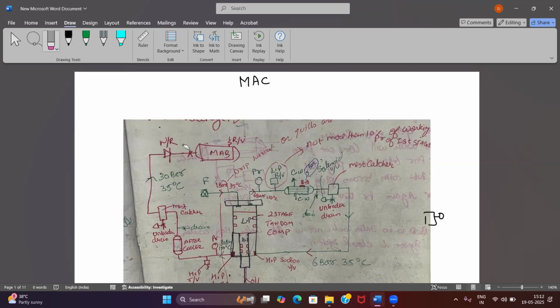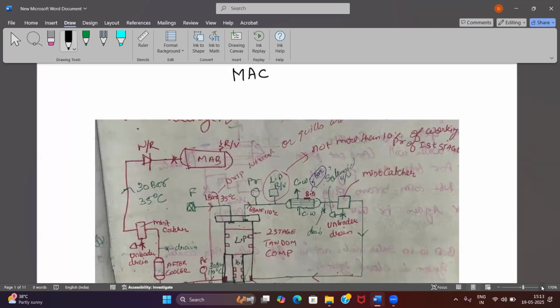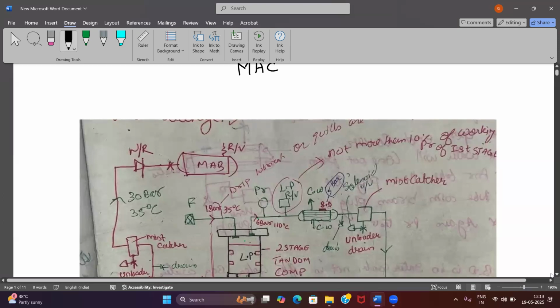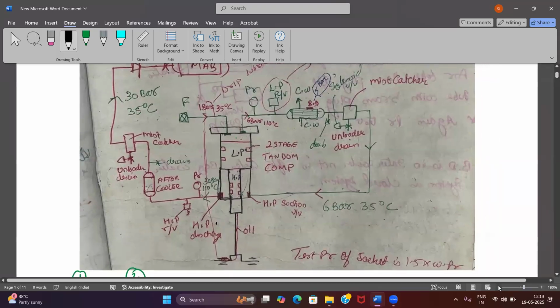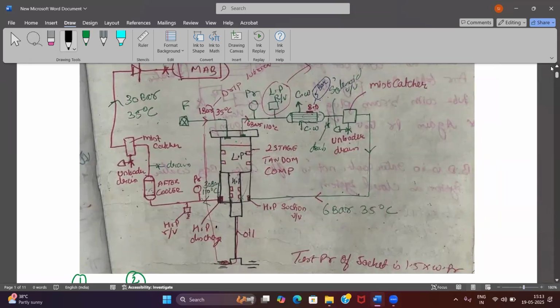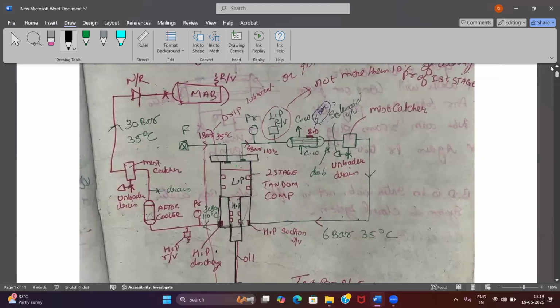As your air bottle pressure increases, the pressure here in the line also keeps increasing, and then you will start to read more pressure on your pressure gauge. Approximately it is equal, the main air bottle and the line pressure after your last stage. All right, so we will go with this example only, 6 bar for now. You understood that it will not be more than 5.5. Understood? Yes sir. If you want to make corrections in your diagrams, you can make the correction also.